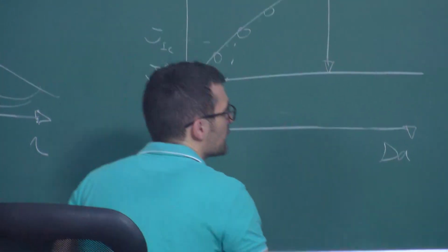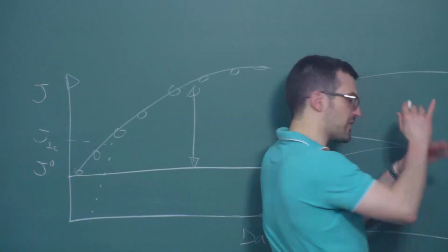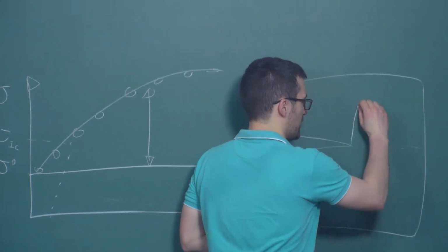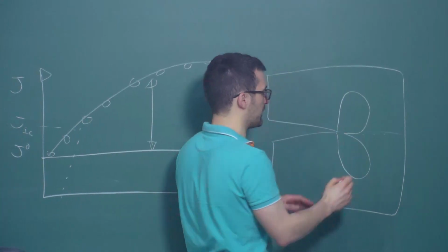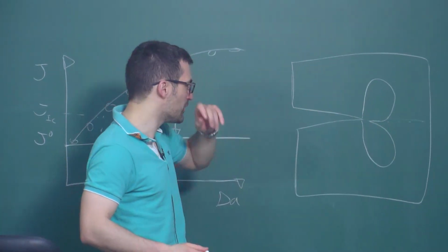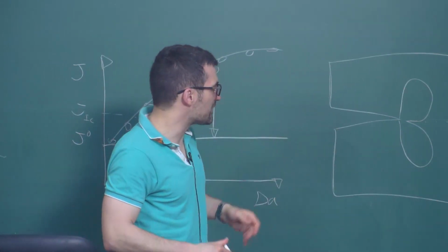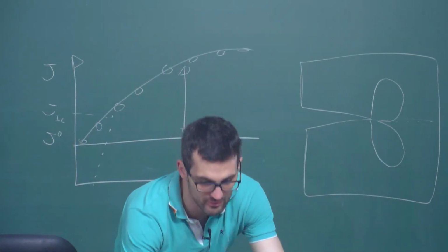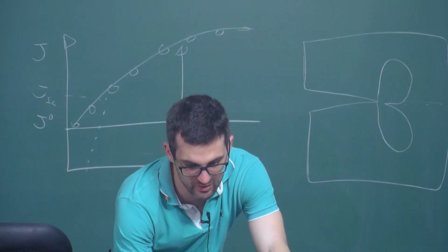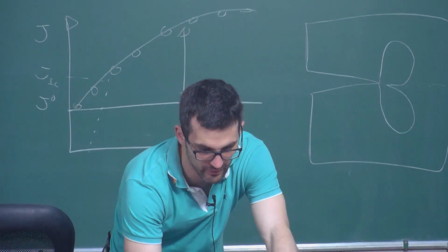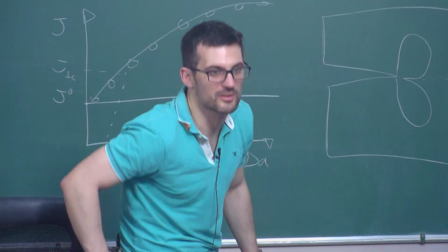Yeah. So the plastic zone, if I think of an isotropic material, will normally look something like this. I mean, it should be symmetric, but it looks something like this. So whether you take this or that, and I think here I'm normalizing by the Irwin plastic zone, that is this one here. This is what Irwin computed as a plastic zone.